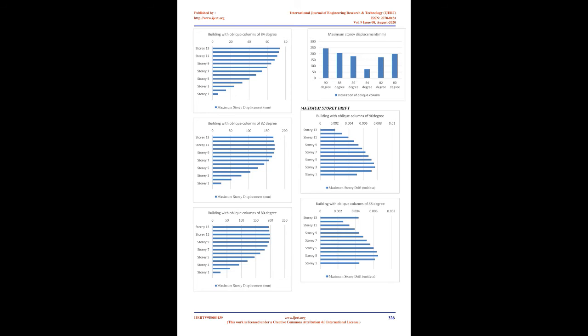A response spectrum is a function of frequency or period, showing the peak response of a simple harmonic oscillator that is subjected to a transient event. The response spectrum is a function of the natural frequency of the oscillator and of its damping. Thus, it is not a direct representation of the frequency content of the excitation, as in a Fourier transform, but rather of the effect that the signal has on a postulated system with one degree of freedom, SDOF. In order to perform the seismic analysis and design of a structure to be built at a specific location, the particular time history record is required. However, it is impossible to have such records at every location.